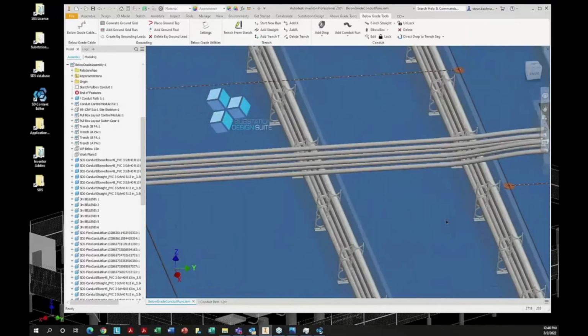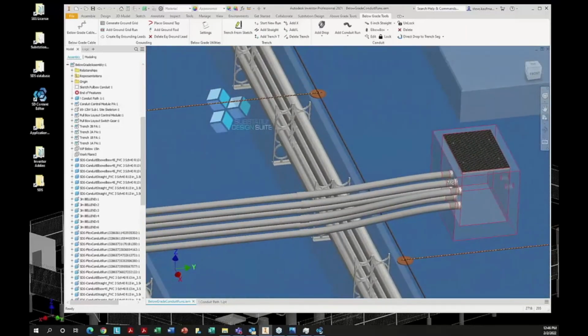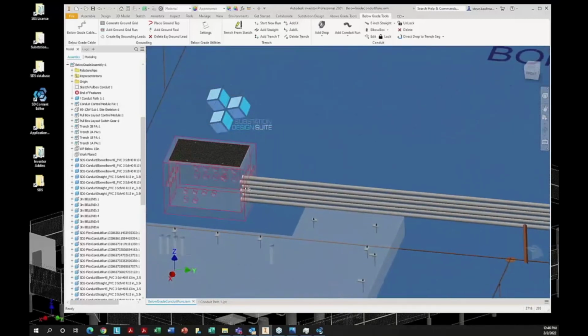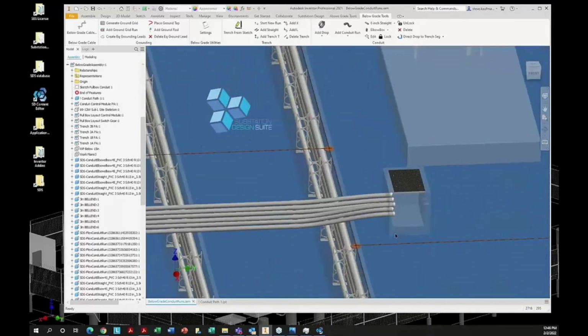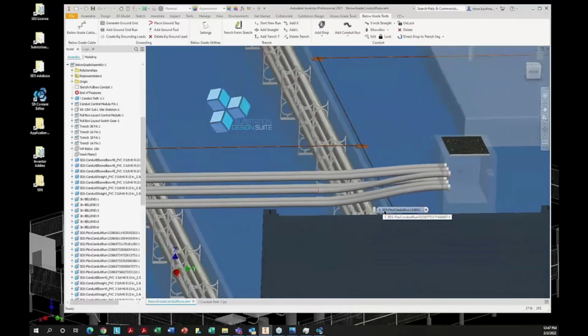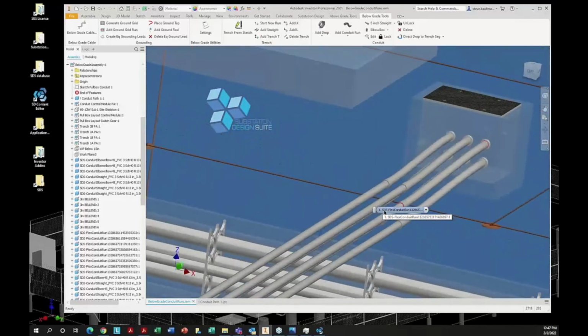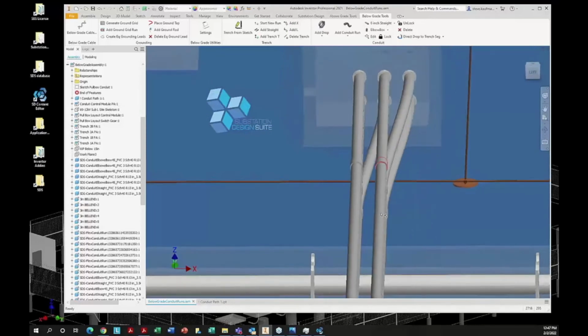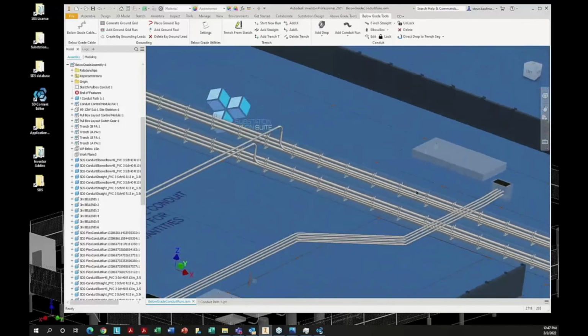No matter what, when I get down to the pull box here, this arrangement is different than this arrangement, right? Again, this is 2 wide, 3 deep, and this one is 3 wide, 2 deep. So now I still have to use my flex conduit to bring it in here. The actual bill of material is going to show this as rigid PVC that would be bent to fit in there. And it's not bent that much. And if you think this is going to be dug out a ways, the spacing could be different down at the bottom. That's wider, and away we go.